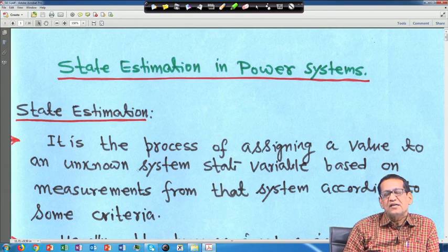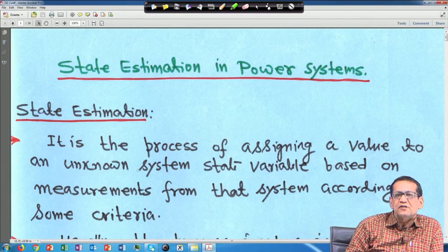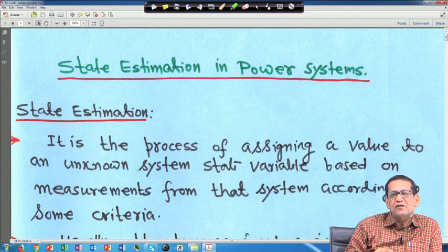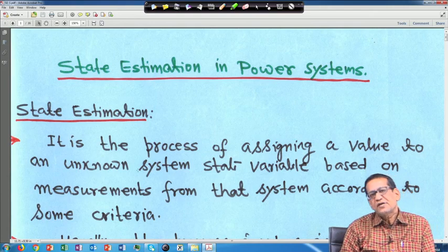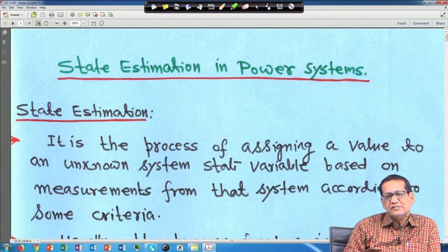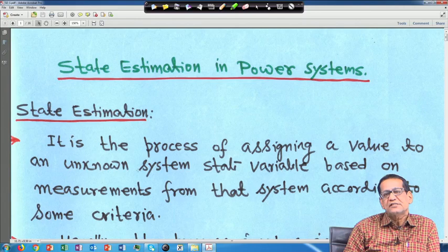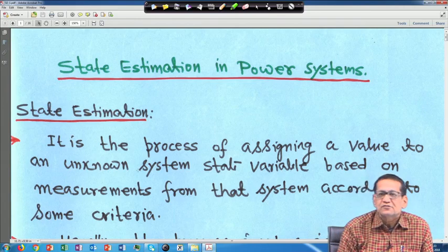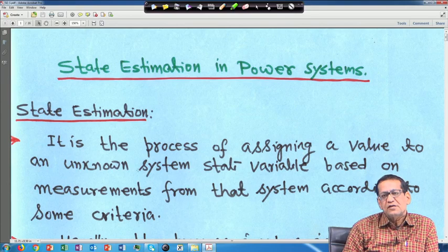Another thing is the accuracy of the instrument; sometimes it is given as plus minus 3% or plus minus 1%. Accuracy means 3 sigma, that is, if you have a normal distribution, it is 3 sigma, basically a standard deviation. So, whenever you measure certain quantities, there is some error. It is not the correct one, it is not the exact one.